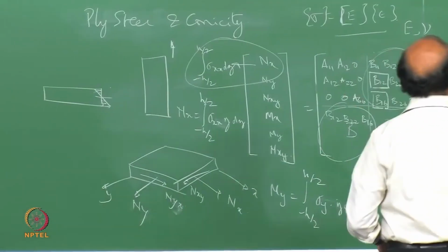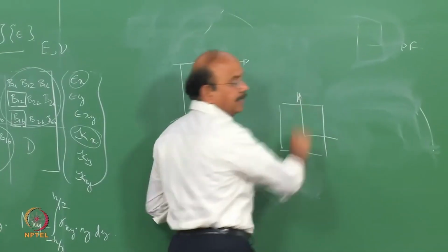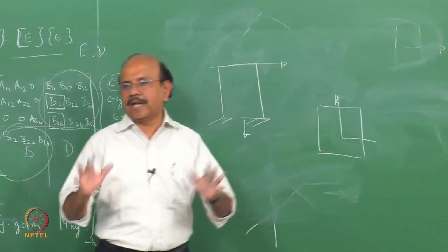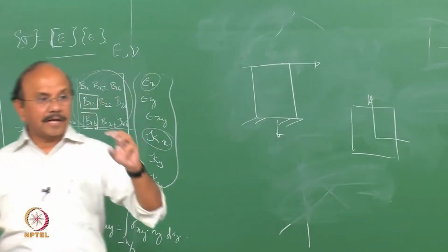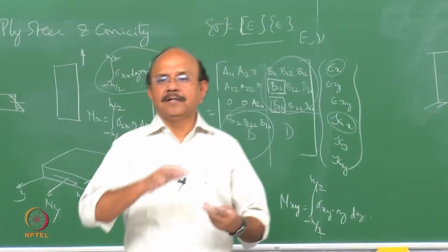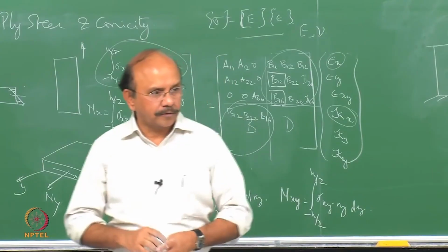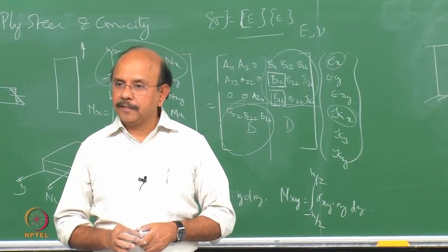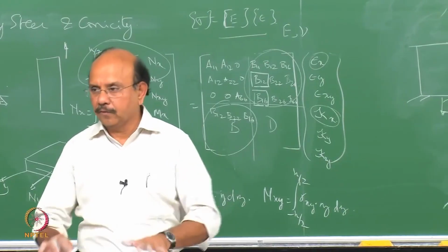So, if I now have a block whose plan is like that, and if I have symmetric axes, it is symmetric bending. It's a simple cantilever beam, it bends. But of course, it's not a cantilever beam as you have studied it, because it is a short, fat fellow, hence shear deformations become very important. There are other things that are happening. And a simple cantilever beam theory, which you have learned, cannot be applied. That's one thing.